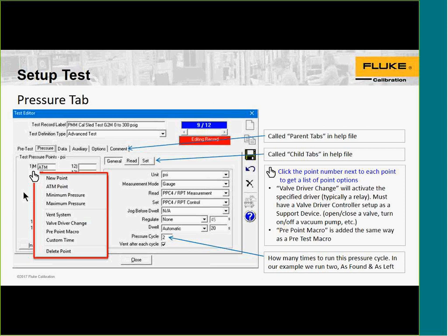This question is, does the piston gauge calculator interface with a piston gauge monitor, referring to 2456, and or LIM? Yes, a 2456 PG monitor or an autoflow controller or LIM, either independently or connected to either of those, would be set up as a support device in Compass for Pressure, or could be set up as a piston gauge, and by setting up as a piston gauge in Compass, that is where you're getting the data, like flow maybe, temperature